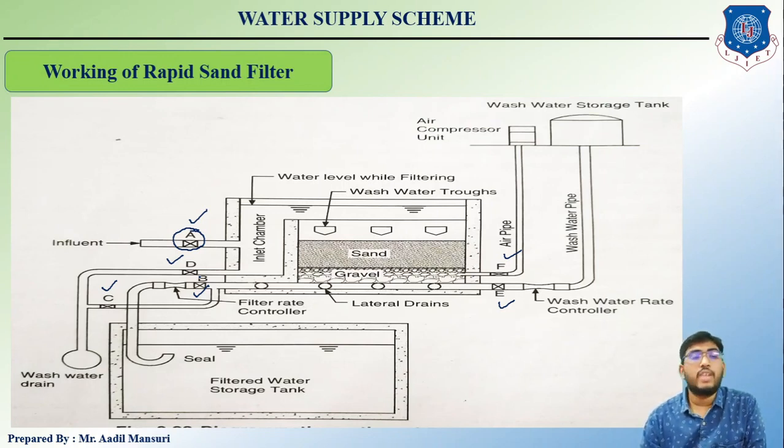As we know, water will enter this chamber with a higher velocity, so in this inlet chamber the pressure will be released. Okay, so it will become still. After that, the water will slightly rise and come into these beds, where there is a sand and gravel layer.